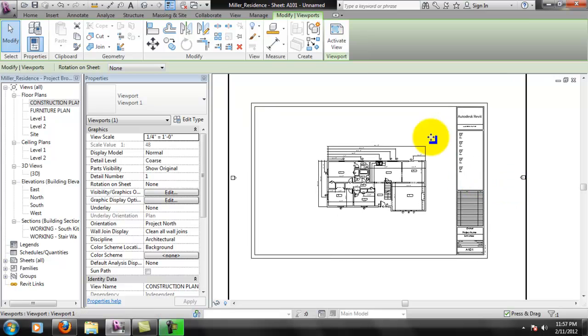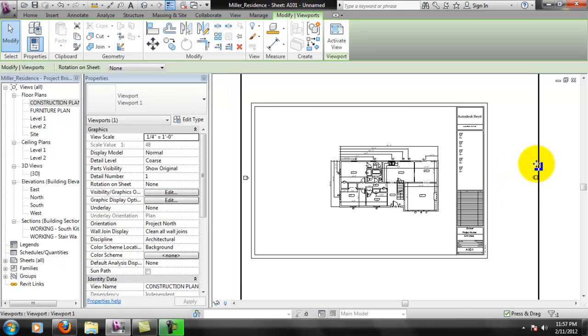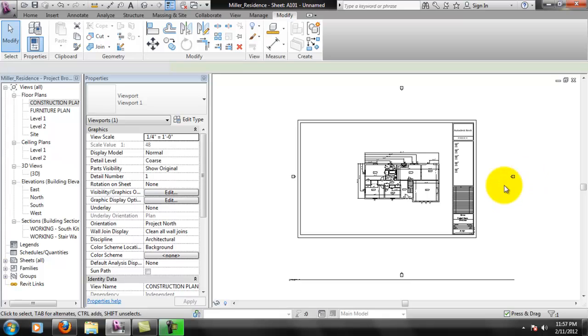And that's because you're usually going to have a lot of drawings and you're going to bind it on the left. So you don't want to put your drawing over here or in the center where it's going to get caught in the binding, especially if you have notes. So you work from right to left. It doesn't really matter whether you work from top to bottom. Usually if you just have one drawing, it's good just to put it in the center. But you're going to want to keep this thing far to the right.